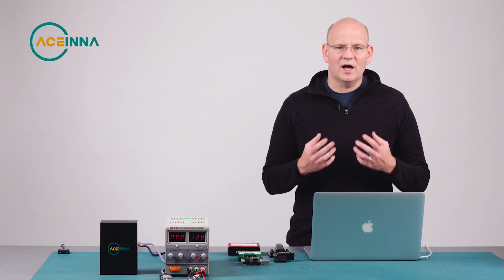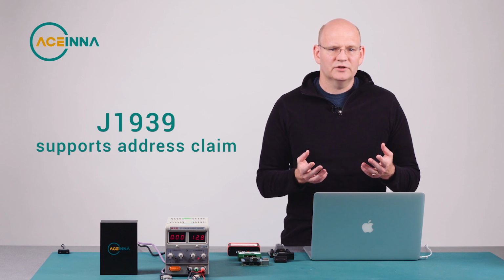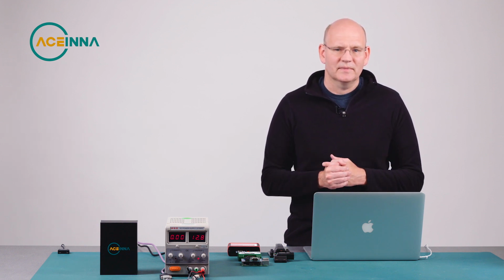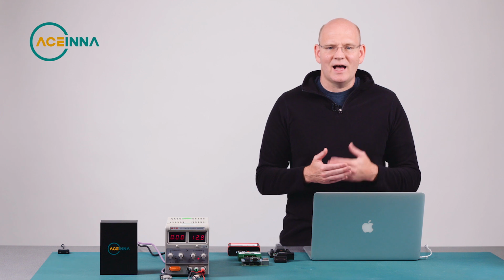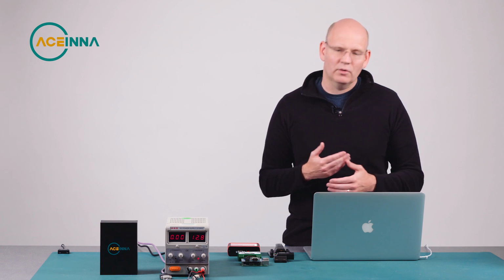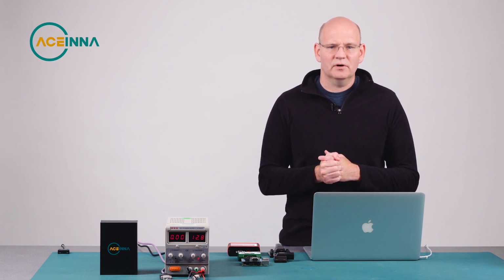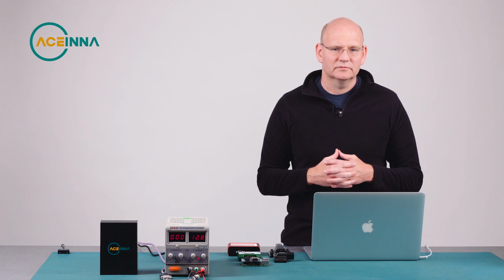And J1939 goes beyond just globally defining messages and data according to a standard. It also supports address claim. Address claim lets a unit dynamically claim a unique address on the CAN bus, as there could be multiple of the exact same device on a CAN bus. In the previous example, without this address claim feature and a standard, it's not possible to have multiple devices of the same type without going in and changing the message IDs of the 2 similar devices. Moreover, ensuring there are no message ID conflicts is purely a manual process with 11-bit IDs. So this is a real benefit of the J1939 standard.